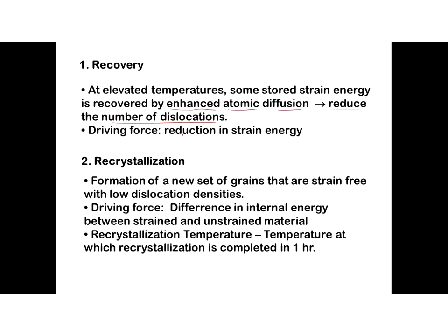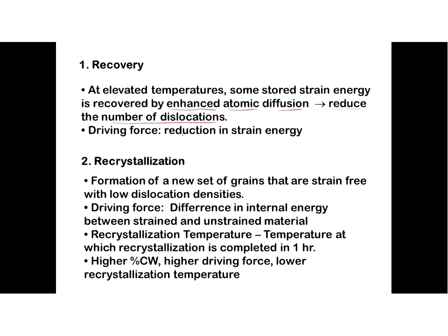The recrystallization temperature is the temperature at which recrystallization is completed in 1 hour. And I believe we usually refer to this as T sub R. It's the recrystallization temperature. The more cold work that's done on a material, the larger the driving force and the lower the recrystallization temperature.